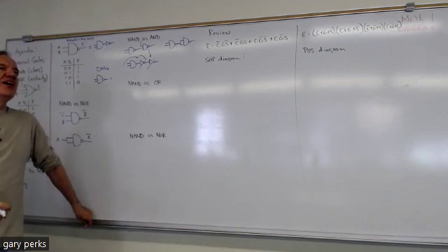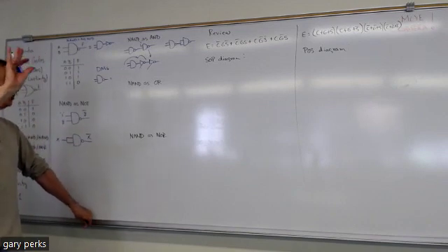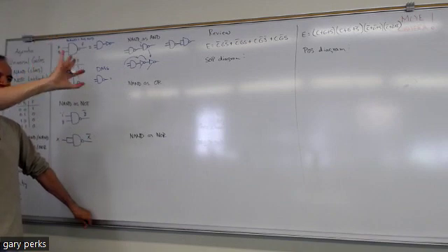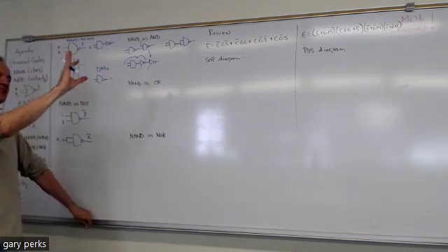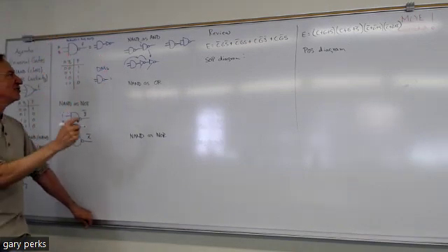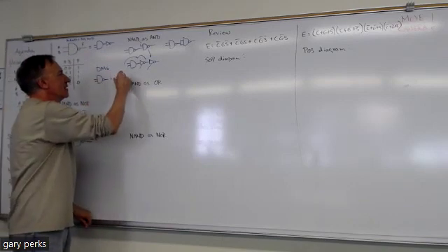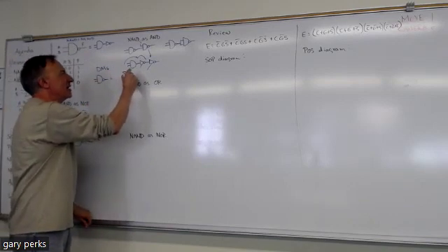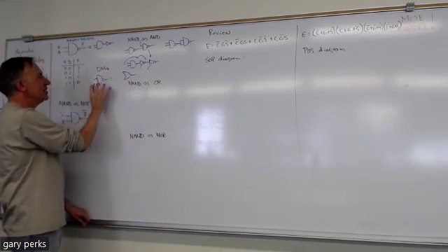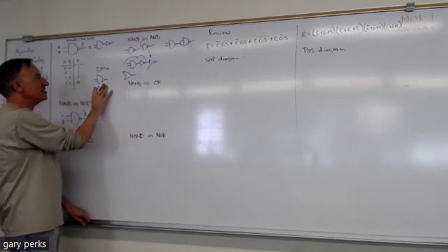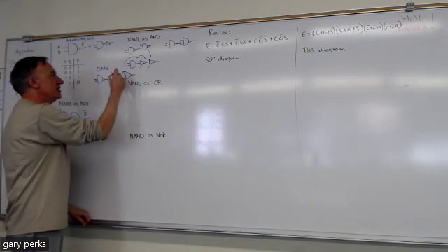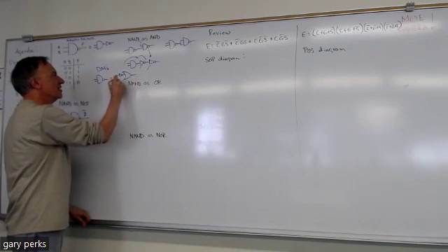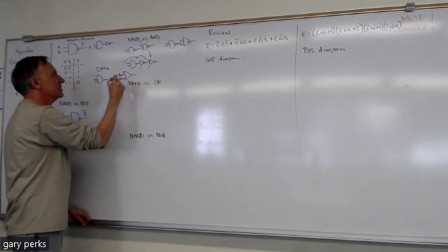OR. Okay, well, you're right that there's an OR and there's a NOT involved, but where are the NOTs? We have an OR gate. Yeah, exactly. So one part of De Morgan tells us that a NAND is equal to an OR gate with inverted inputs.